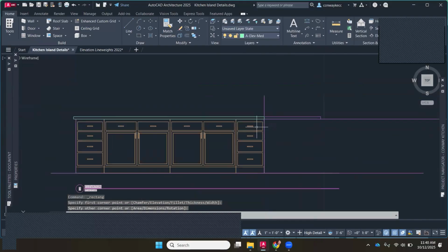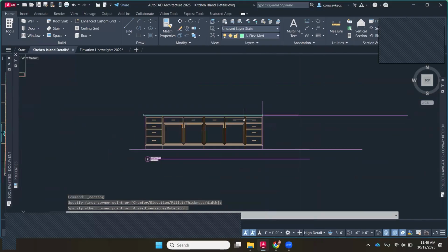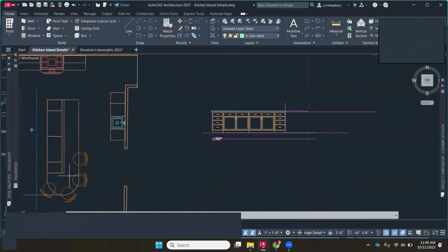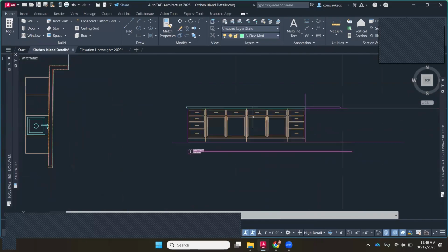Okay. So now in my case, I'm planning to have this little kind of wall behind my cabinets that helps support this long countertop and have it at bar height. So bar height now I'm going to use from the ground is 42 inches tall. So I'm going to offset that to 42 inches tall. And then I'm going to come up here.